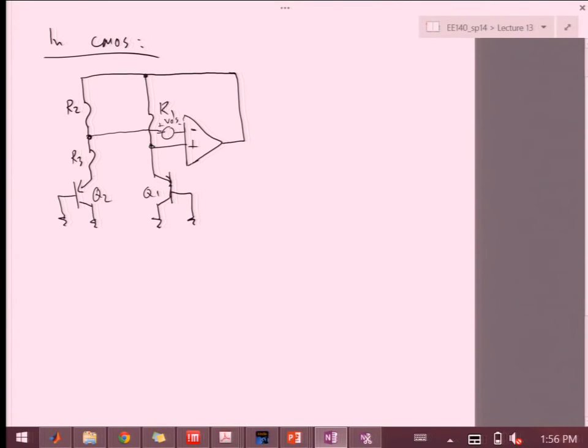And then I have my VBE, or this is the VB, and then I also have the difference of the two VBEs to give me VT. And how's that going on? So let's first take a look at what is the delta VEB. So let's say VEB1 minus VEB2. And VEB1 will be VT ln of I1 over IS1 minus VT ln of I2 over IS2. Right? So these are all just our bipolar equations.